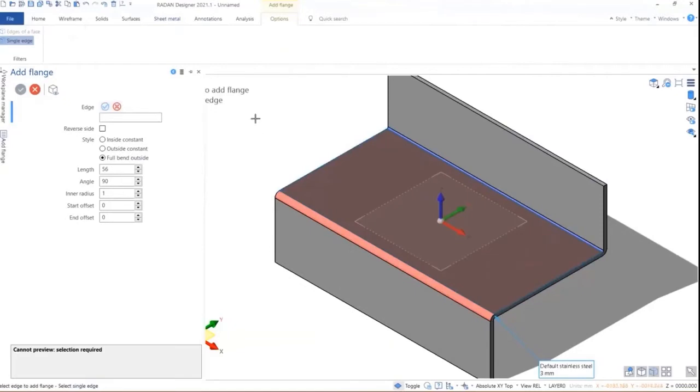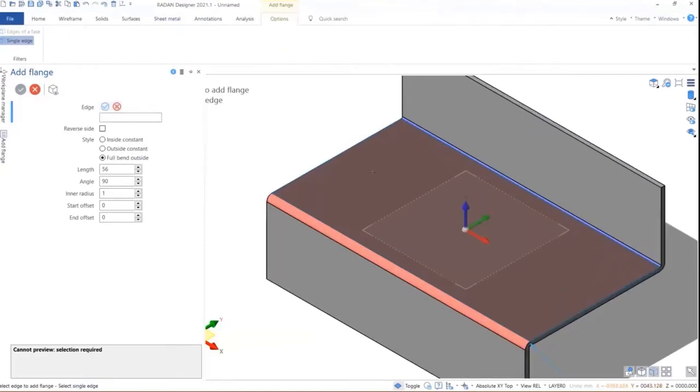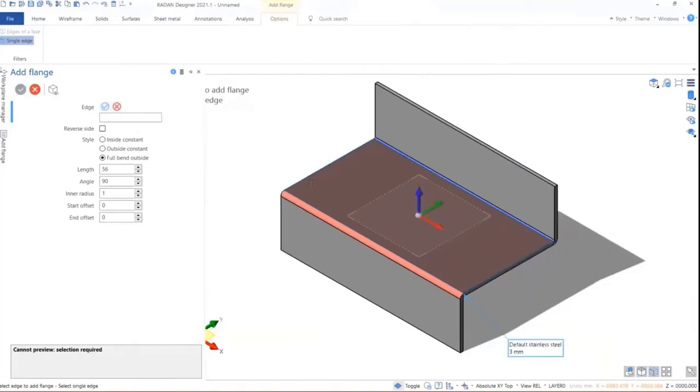Now I know it's incorrect because of the color of the bends. Down is red, up is blue, but if it's pale red, that tells me that that is an incorrect radius for the V width that I've selected. And the pale blue indicates that that's an incorrect bend radius. Okay.